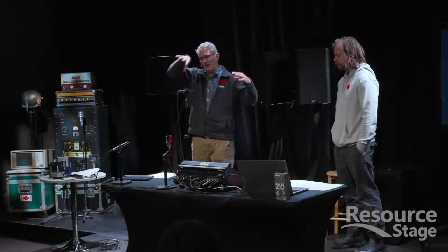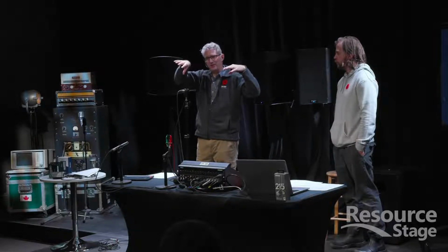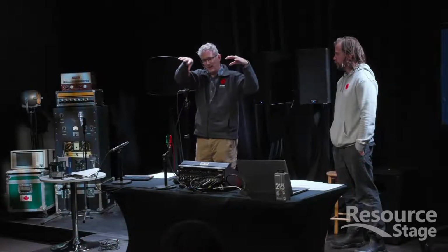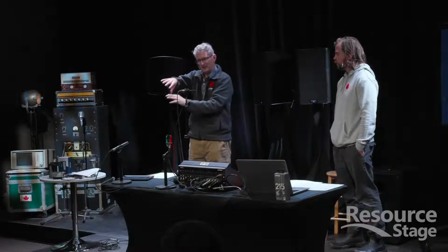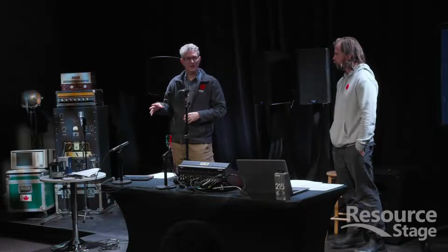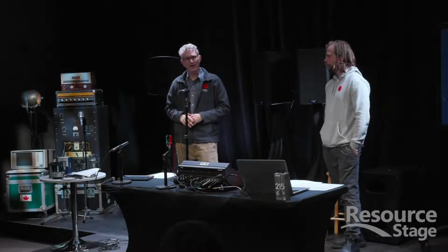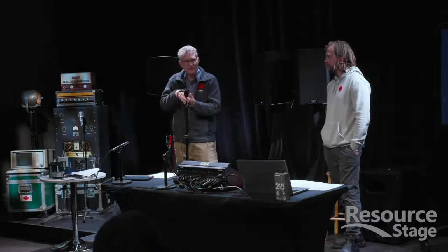So what we do is, the speaker towards the back of the auditorium, what we call the delay loudspeaker, we will physically delay that in time so that the sound emanates from it after the first one, so that anybody sitting in the back, it actually sounds as if the sound is coming from the front loudspeaker. It's really neat to sit there and play with the delay while you're listening, and be able to get it to the optimal setting. It's a really important thing to do.